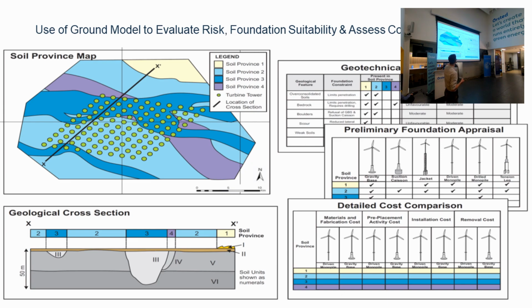I guess some of the issues with this type of approach are that the soil province model doesn't necessarily explain the geology very well. It's very rare that geology has these kinds of physical boundaries. Usually there are gradational changes, let's say in the nature of the fill, which may be more sandy and progressively more muddy as we go laterally. So it's important to be aware of that, and your soil provinces and the soil profiles that relate to those need to have appropriate bounds on them. And so the geologists need to work with the engineers to identify what are appropriate bounds.